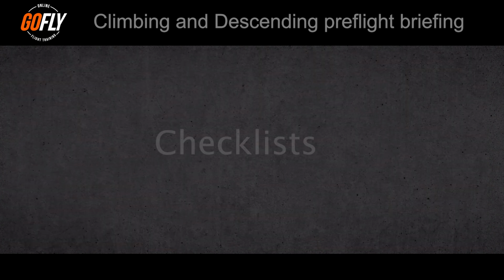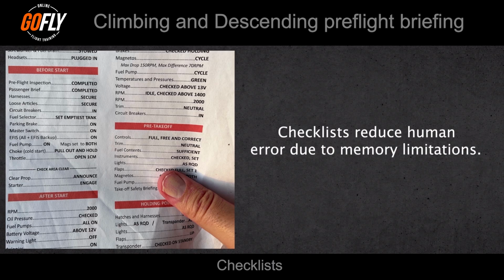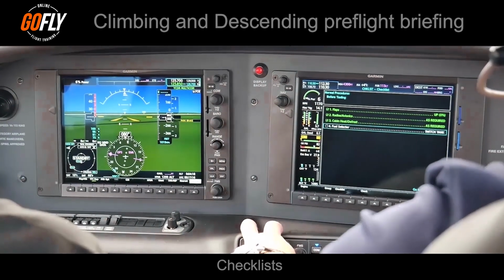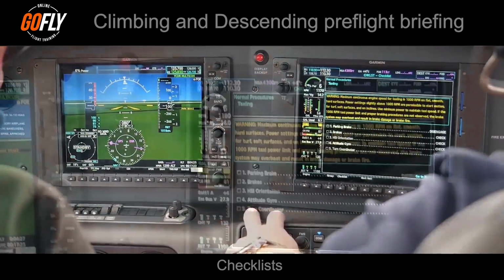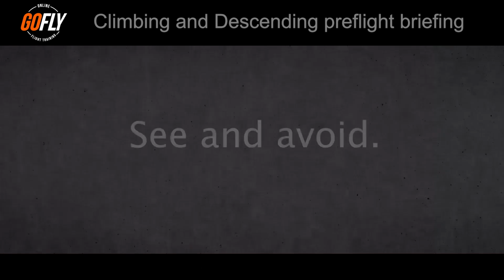During your flight training, you'll be introduced to the use of checklists. Aircraft checklists are important as due to the complexity of the many items we need to check on an aircraft, both before and during flight, it is not reliable to rely on human memory alone. Most aircraft have standard checklists supplied with the pilot operating handbook. It is vital we use these checklists every flight so the pilot does not forget to check a critical item, for instance, forgetting to select flaps on takeoff.